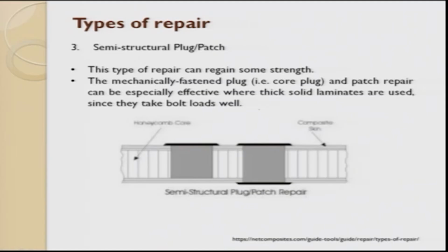The next one is semi structural plug or a patch. So, this type of repair can regain some amount of strength. Mechanical fastening plugs, a core plug or a patch repair can especially be used where thick solid laminates are used, since they take bolt load as well.